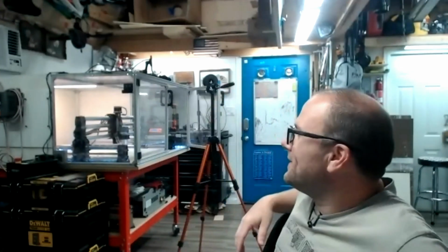Oh, it does ship the controller with the e-stop pushed way down. I thought I was undoing it, but I was not twisting it hard enough. So twist it really hard, and you'll feel it snap up. Not every e-stop button's the same. So if it doesn't turn on when you flick the switch, check your e-stop first. And they are checking everybody's 220 and 110 now too.